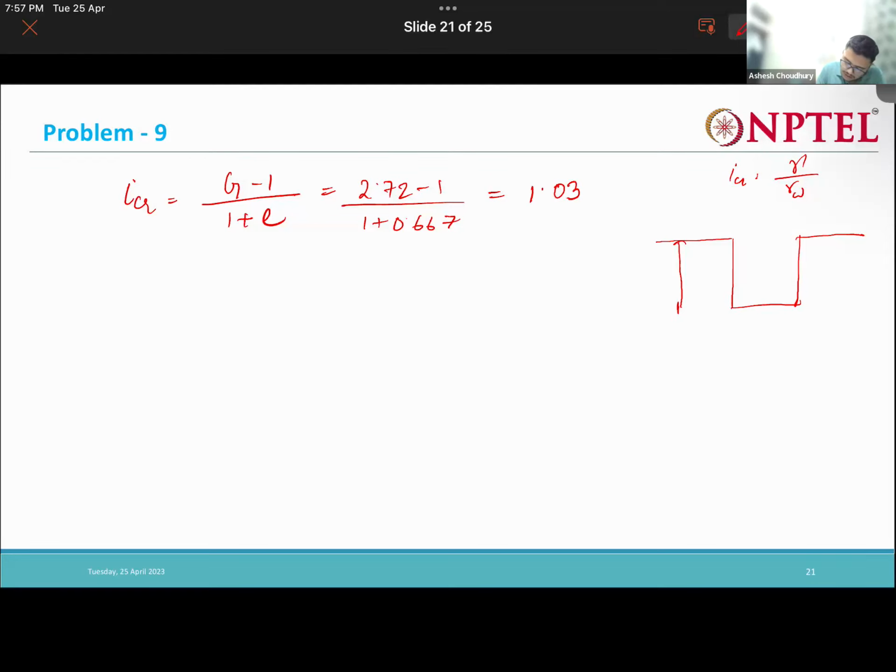Okay. So this flow will actually be required to cause the quicksand conditions. And also, if a head of 3.09 meter is there, that will cause a quicksand condition. Quicksand condition means water will completely come, and effective stress will be zero at that part. Okay.